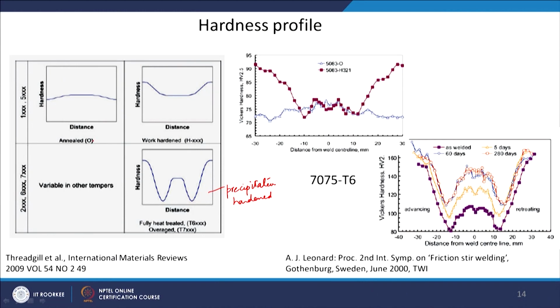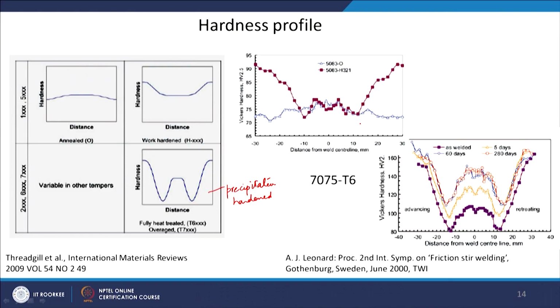If you take a well annealed material, okay, which does not have precipitates, does not have dislocations, only in this case maybe you will be able to see a slight increase in the hardness due to grain refinement. Okay. So, there are three classes of material, and the actual results are shown here in the graphs.